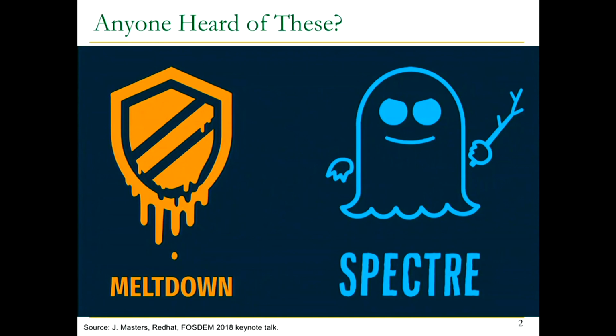The vulnerability is really due to what's called speculative execution, which is doing something before you actually know that you're supposed to do it. You need it. So you guess, and you execute some part of the code. If your guess is incorrect, you've executed something you're not supposed to execute, and it may bring in some data into the processor that some other person who's very intelligent and very sophisticated can infer. That's the idea. And this happens because of the way we design processors today.